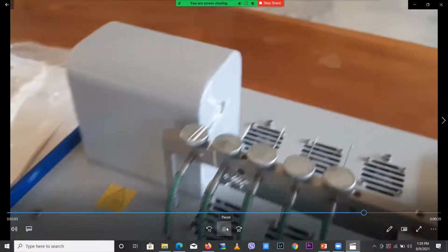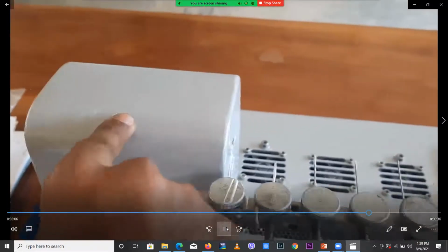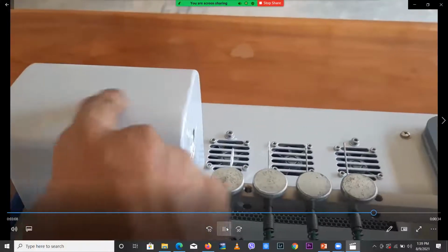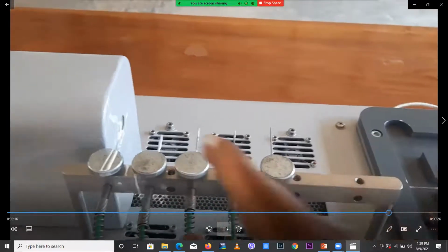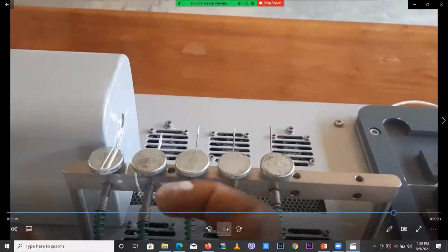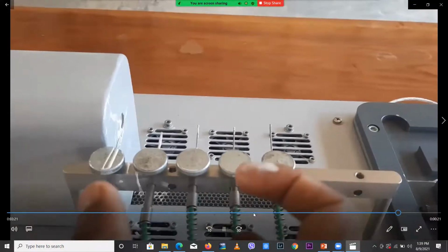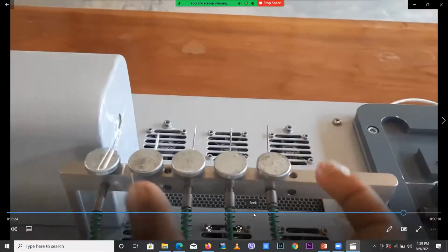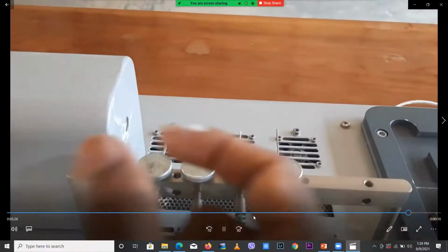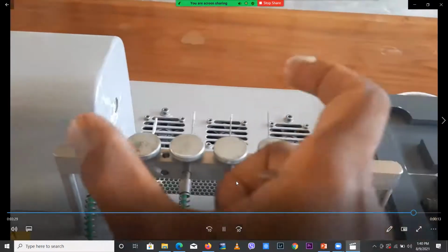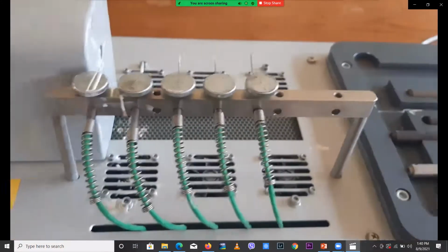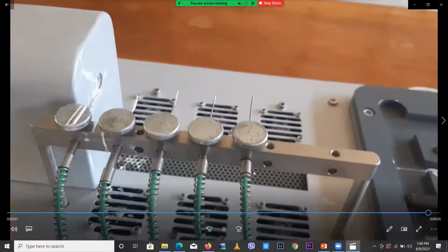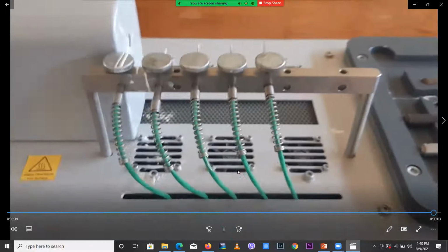So this is the heating controller. From here the heat will be produced, and the heat will flow from the left side to the right side. So there will be a temperature difference, and we also know the standard distances and length of this specimen. If we know the temperature differences, cross-sectional area and length, then we can calculate the heat flow rate of the material. So first we will do it for the copper.